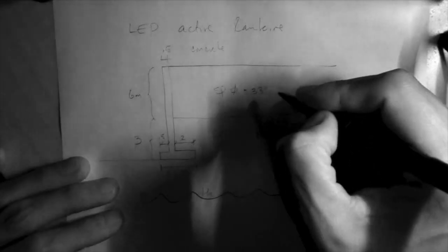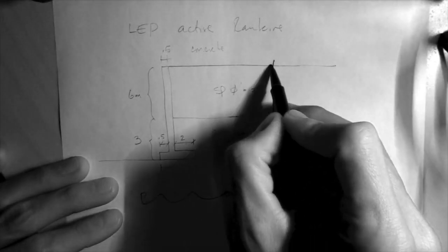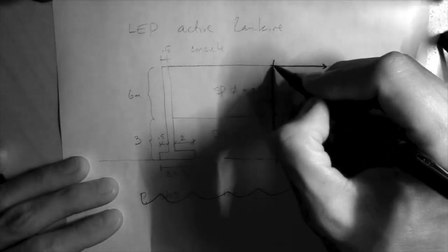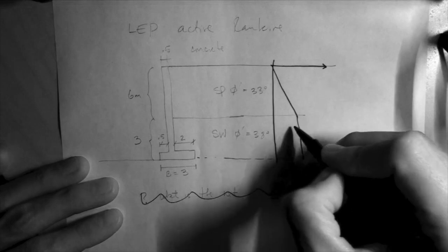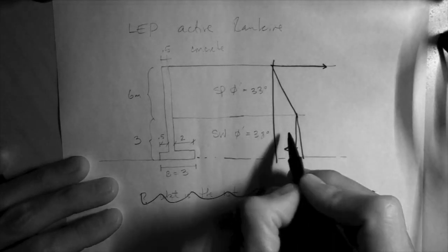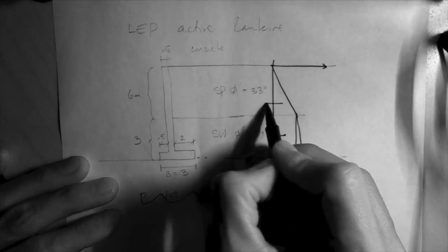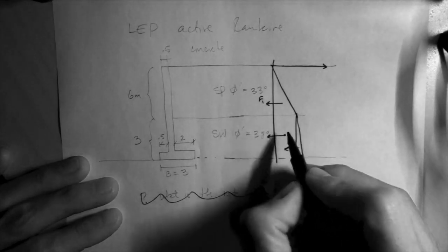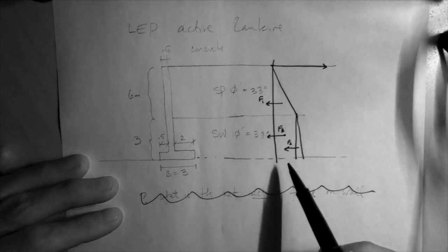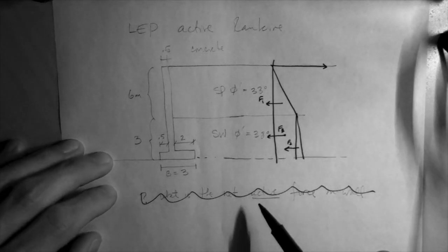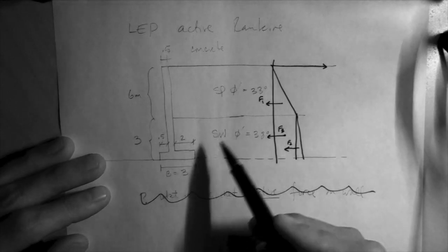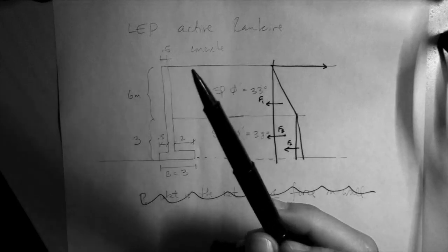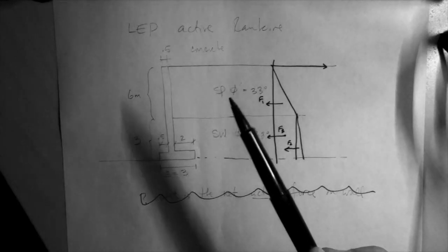So those forces, F1, F2, F3, impose moments about points, everywhere really, but essentially we have to select a point about which we believe the wall will rotate due to those forces.